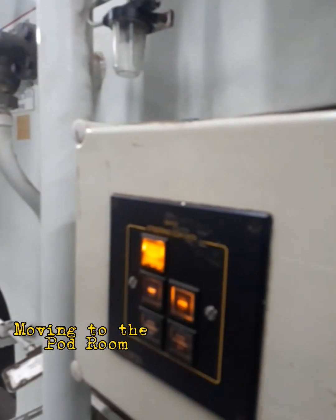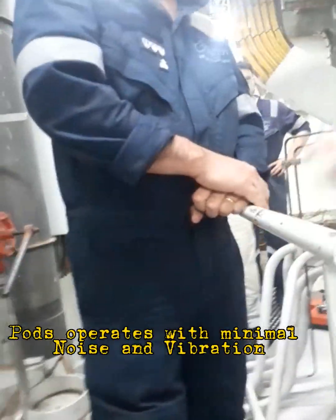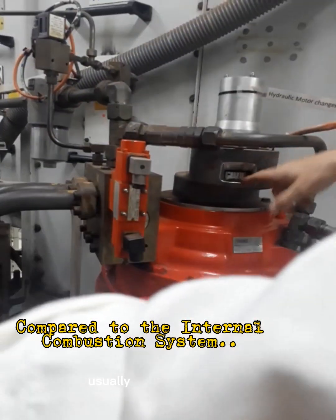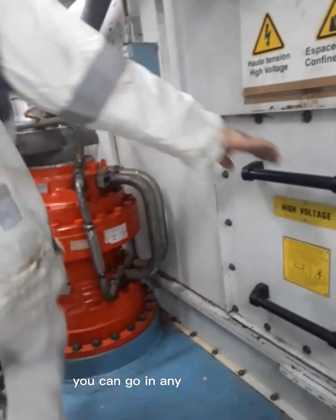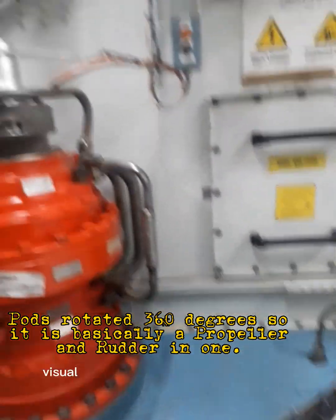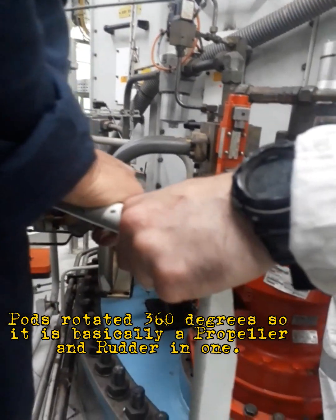Now let's move the pod in some way. That's why we run the steering pump, to keep the pod on the position which we like. Usually we put 270 degrees just to open the passage to the 170. It's very easy to go inside. You can go any degrees down, but 270 is the best way to go inside. Pesho, give me one pump on the local and start the pump. The other one also from local. Start one pump, or both of them.